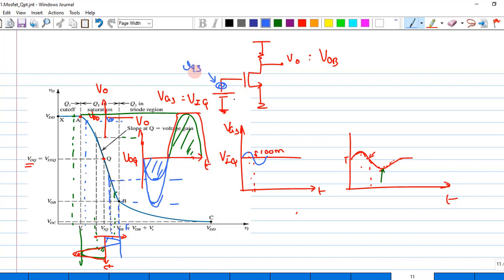Whenever I talk about the small signal or incremental voltage, I would represent the values in terms of small letters, the vgs. And whenever I talk about the DC or the Q point, I always use capital letters, like VGS. Now I also have a third form of notation, which I call the composite form, which is a combination of both. Is that clear?